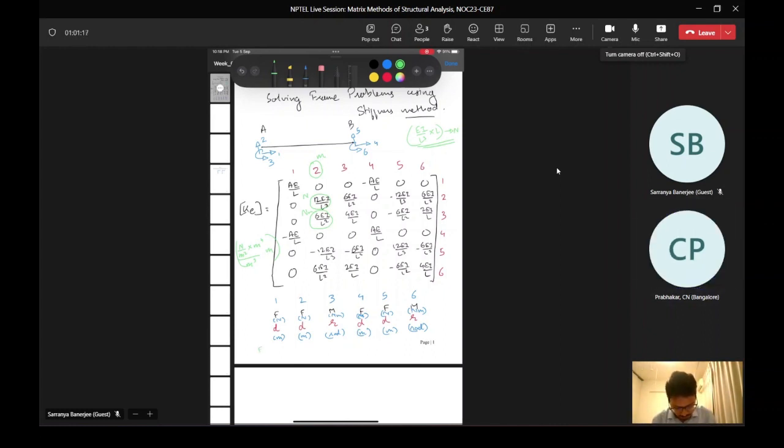So we know EI by L cube into L will give us Newton. That's fine. Now when we are talking about the third row and second column, we want EI by L to the power n, we don't know n, into, we already know second column, so we are already multiplying with L. It should give us Newton meter. Exactly. So now you will find that n should be 2. N has to be 2.